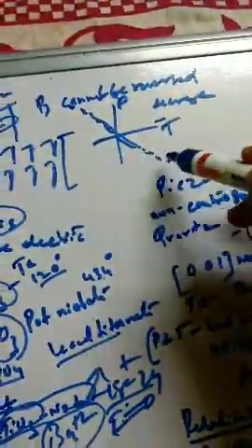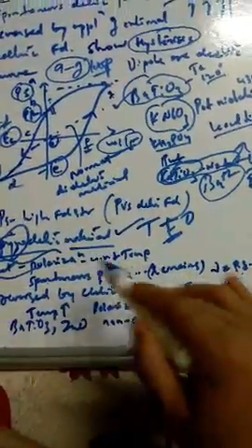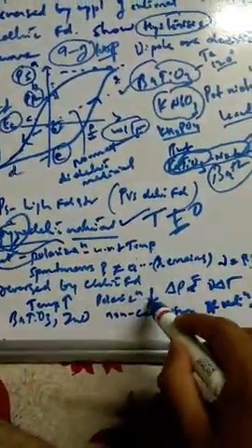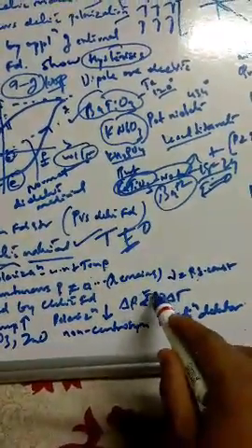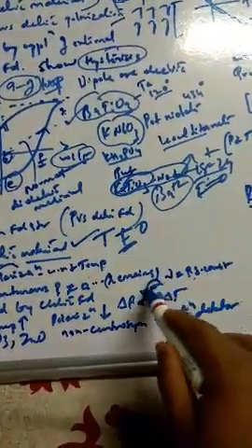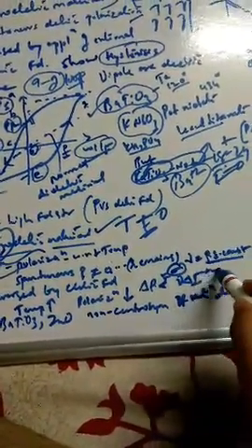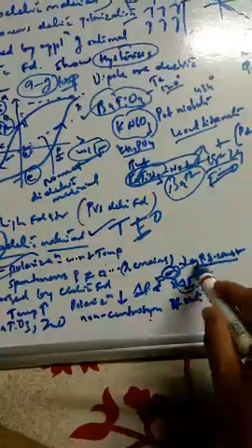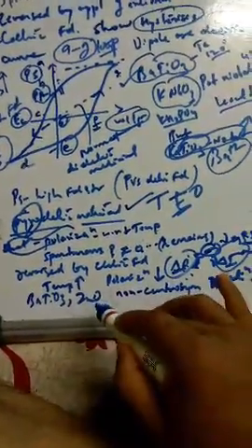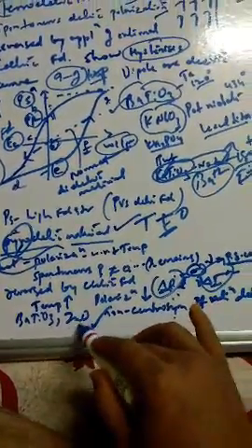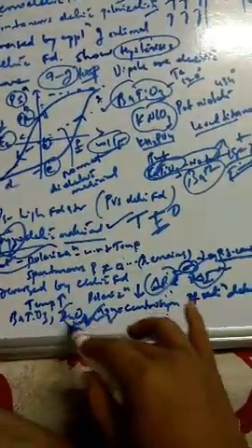It is not reversible and will not show hysteresis like in a ferroelectric. Polarization decreases as you increase the temperature, and it is given by delta P equals nu delta T, or sigma delta T, where sigma or nu is nothing but the pyroelectric constant. Delta T is the change in temperature, and delta P is the change in polarization. An example is zinc oxide, which has a wurtzite structure, or even barium titanate. All ferroelectric materials are also pyroelectric.